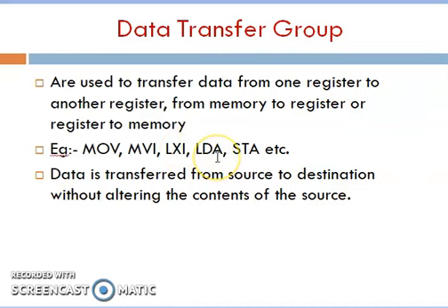LDA is load accumulator with the content of a specified memory location. LDA will be followed by an address which is a 16-bit address. Then STA 16-bit address. Store the content of the accumulator in the specified memory location.